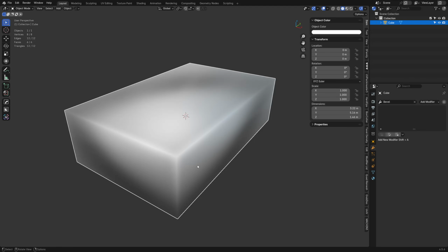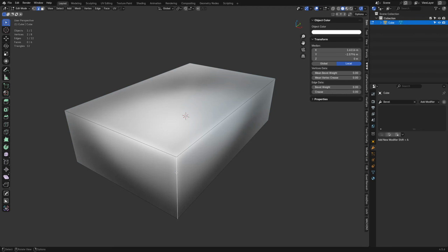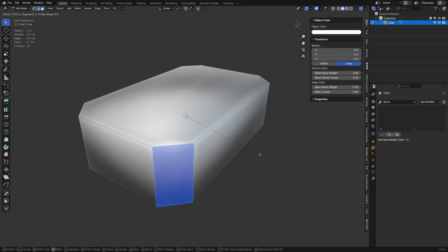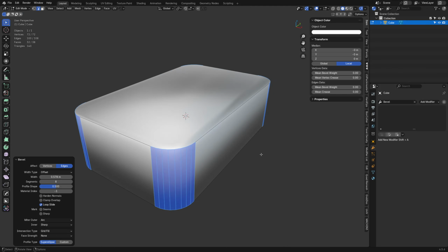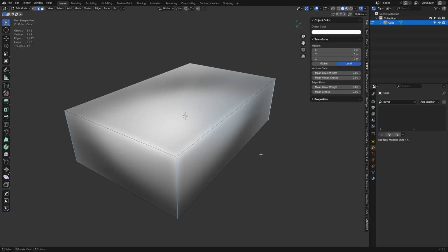But what if we wanted that kind of same chamfered effect on a cube like this, right? Well, we could go through and bevel all these edges first, and we can do it destructively, which is fine. There's nothing necessarily wrong with this. But if we end up wanting to use a remesh workflow and we're planning on remeshing this to high resolution and sculpting on it or something like that, sometimes this is a problem because they're not high enough resolution and then it doesn't smooth out very well. And so we can do this non-destructively. And this is where it's kind of fun here.